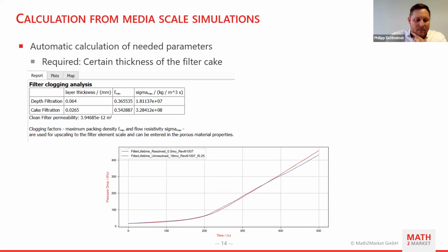Yeah, so this has several effects we need to consider. So the first is the domain size we have. The software Geodict is developed in that way that we can directly simulate on microscale. So we don't simulate on small domains like 100 voxels in each direction. We really simulate on 1024 voxels in each direction with no problem.